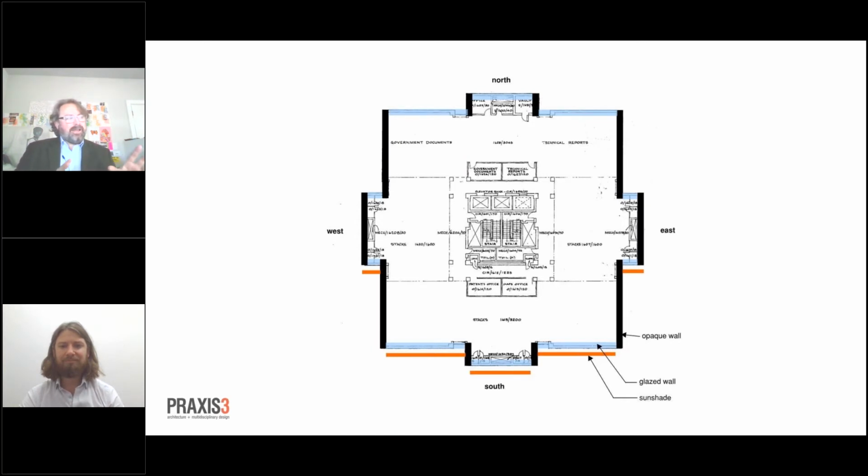The black lines you see are solid masonry mass walls. So these are brick walls, no air cavity, grouted full, CMU backup wall, brick mass masonry wall. That was the condition on all four sides of the building originally.